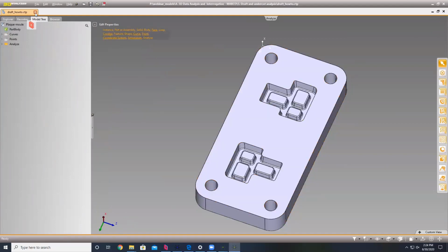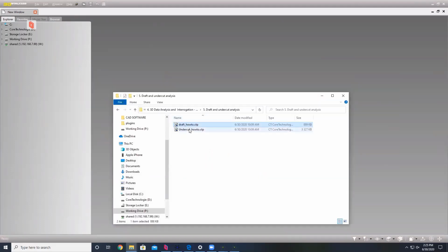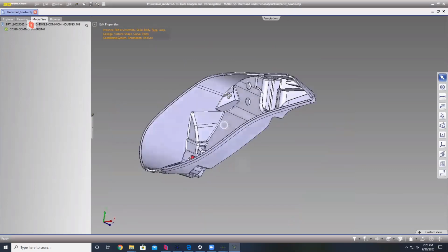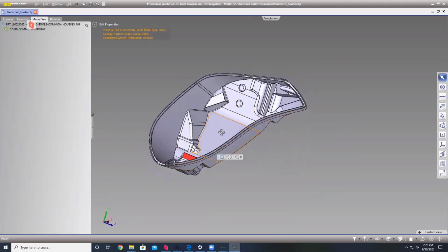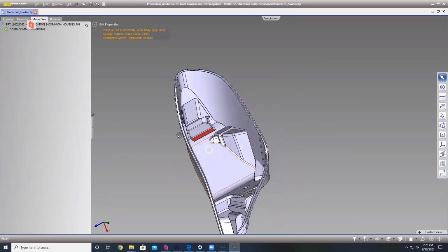So again, this is for molding operation, but the undercut will actually, as opposed to just giving you the angle and then you deciding what to do, the undercut will tell you the parts that are actually producing geometry that will not be easy to eject because it will be behind a part of your mold. For example, in this mold here, you see that it's complex.